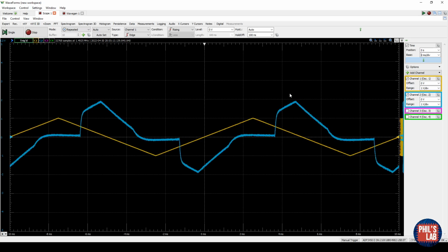So let me play around with the hold time and pay special attention to where we are attacking. And remember, the hold time changes the time before the noise gate engages. So decreasing my hold time makes my system attack faster, and increasing my hold time makes my system respond slower.